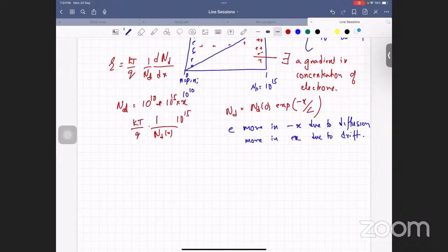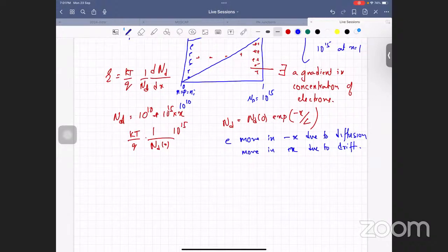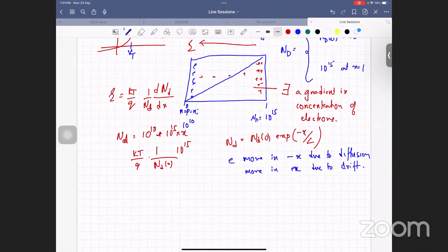At infinite time, this piece of semiconductor is in equilibrium, in a condition like this with diffusion. It cannot be at infinite time. There has to be some kind of equilibrium established between the drift and the diffusion, and you will not have any more changes. If you look at dN by dx, there is no net current. Initially, when there is diffusion, is there a diffusion current? Of course, there will be some diffusion current for a short time.